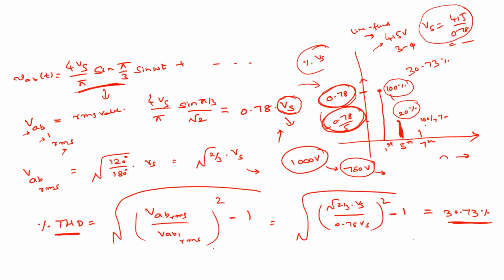Sir, one doubt: the fifth harmonic magnitude is negative, no? That is magnitude, and that is why you cannot represent negative values in the spectrum. The only thing is that it is rotating in the counterclockwise direction. In that case, for the phase angle, you may get negative values. One is rotating at minus omega t.